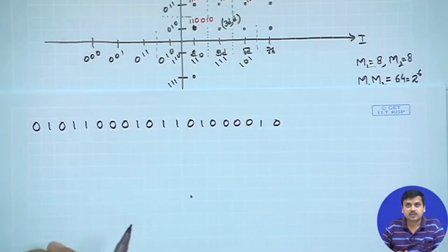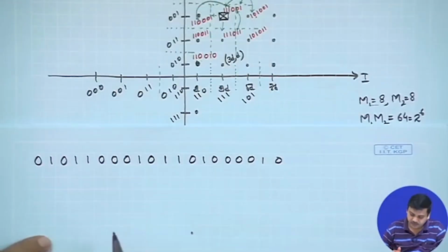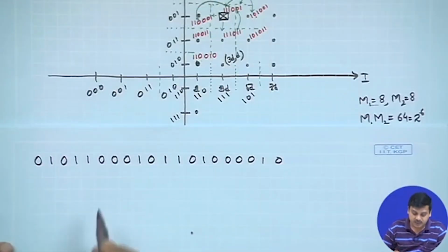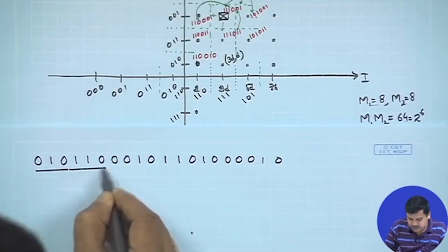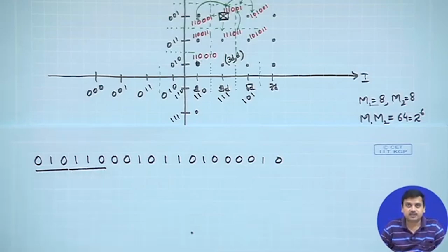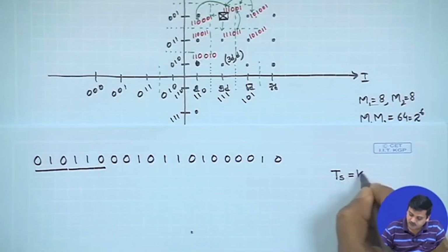So, now the question is how do you do a QAM constellation generation with this. So, what we do is, suppose we have to take this constellation and you have to take 6 bits. So, you can say I would take these 3 plus these 3, that is 6 bits to choose my first symbol.